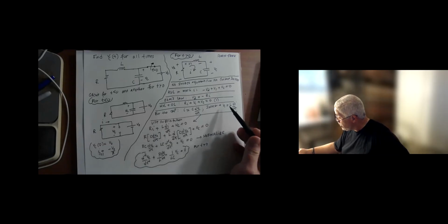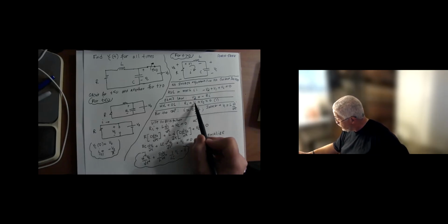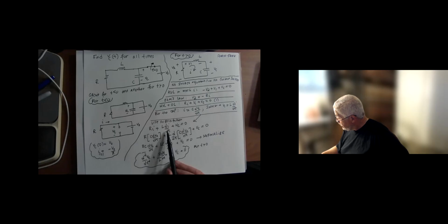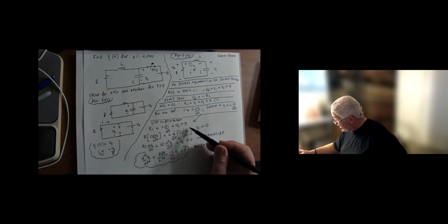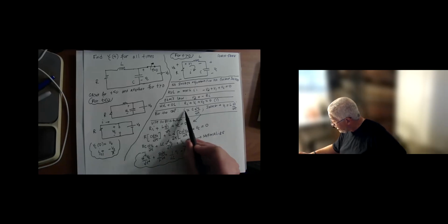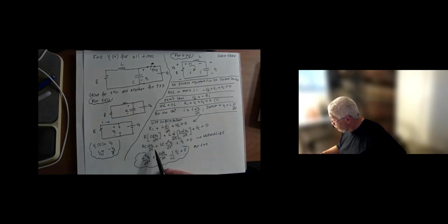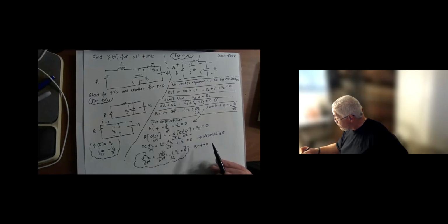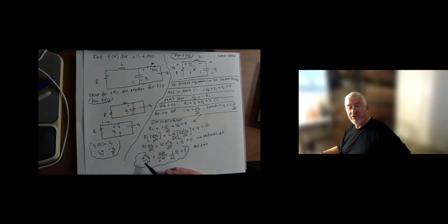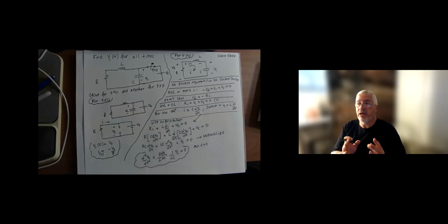The first thing I do, I use the inductor equations. And when I do that, anywhere that I have V1, so I have V1 only here, I basically put the inductor relationship. Okay. And then I bring in the capacitor after that. So anywhere that I have I, I essentially put it as C dVC/dt. That's what you got here and here, which leads me to this. The last step here is to normalize such that the highest order derivative has a unit coefficient. And that's something we're going to do in a standard way when we discuss how to solve this differential equation.